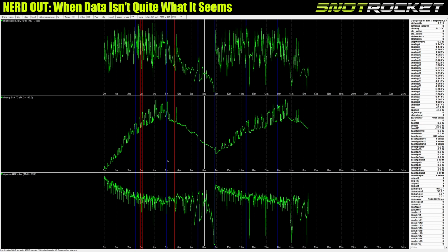And just for information, the first stint didn't have the fan active on the oil cooler. The second stint did have it on, and you can see there's a slight change in the rate of increase in oil temperature over time between the two tests. So the fan definitely seems to do something. It definitely slows down the rate of increase in oil temperature, but you can see that it's only when I start lifting and slowing down that the oil temperature really stops climbing. So oil cooling isn't sufficient at the moment, but this is definitely some good data.